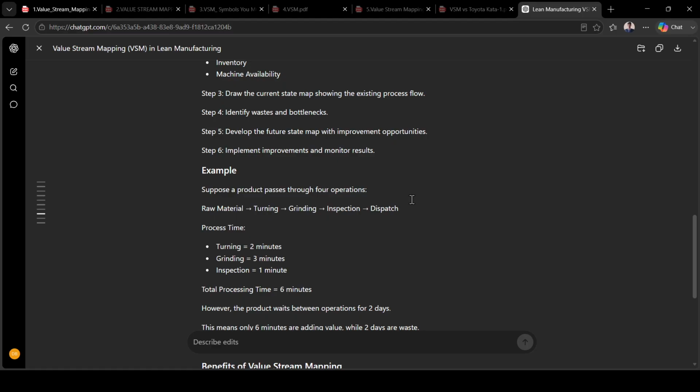Examples. I will give an example so you can easily understand everything. Suppose a product passes through these operations: raw material, turning, grinding, inspection, dispatch. Process time: turning 2 minutes, grinding 3 minutes, inspection 1 minute, total process time 6 minutes.